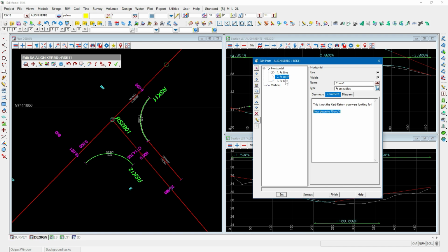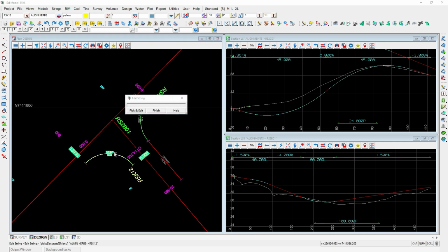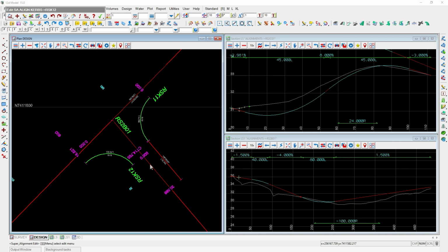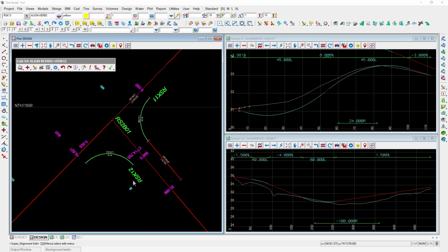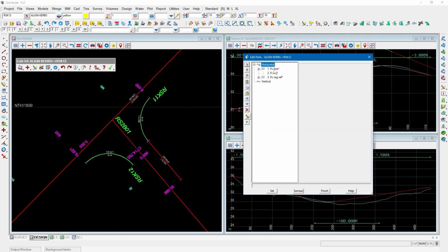So that one's pretty easy to see how it was set together, just the simple fixed and free in between. We took it to the next level, I guess, for the other side here, where we thought we'd do the same thing, but having it fixed means that it's just set off coordinates. So if either of the two roads at the intersection were to update or recalculate, then unfortunately the curb return wouldn't update. So to build it a little bit smarter, we would have the same sort of idea, fixed,